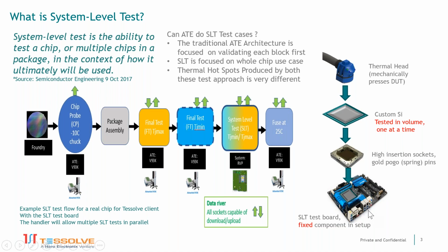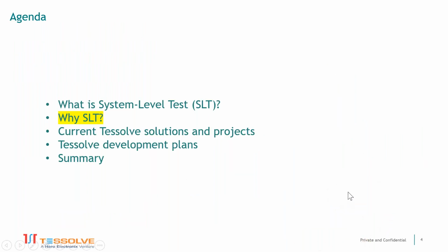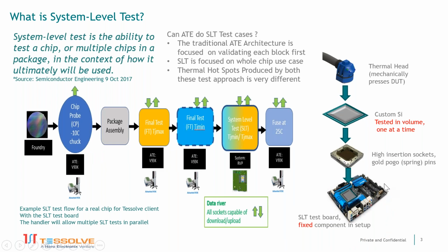So this is a typical SLT setup. You've got a reasonably complicated board there, because you need to put the chip into a system level context. So you're trying to mimic how it will be used eventually. It's like a validation board.